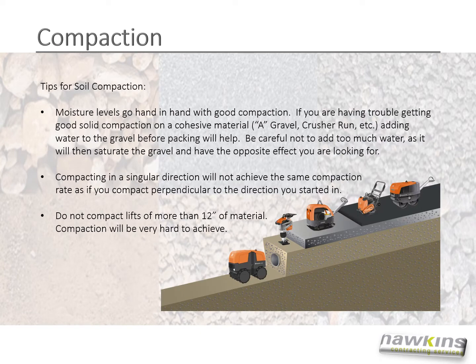Tips for soil compaction. Moisture levels go hand in hand with good compaction. If you are having trouble getting good solid compaction on a cohesive material, such as a gravel or crusher run, adding water to the gravel before packing may help. Be careful not to add too much water, as it will then saturate the gravel and have the opposite effect